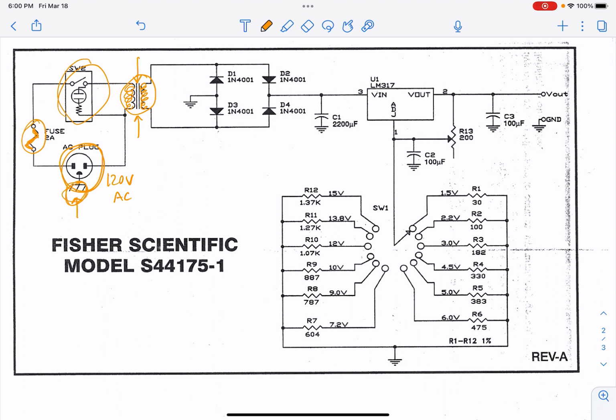And these two parallel lines would represent an iron core, which would intensify the effect of the transformer. And this transformer will be allowing you to step from 120 volts down to 12 volts. And the way that you're able to step up or step down the voltage is by going from lots of turns of wire to a relatively few turns of wire in each of your coils. And you'll learn more about that in a later chapter.